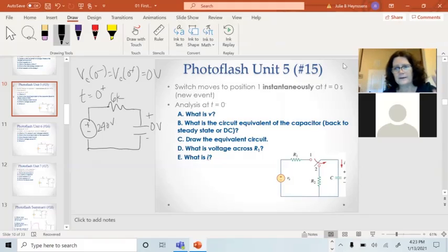And I was writing a KVL equation. So KVL tells us the sum of the voltages around the loop equals 0. I already defined my polarities looking like this. I'm going to go around the loop clockwise, starting with the voltage source. I'm going from minus to plus, so that is an increase in voltage. That's 240.